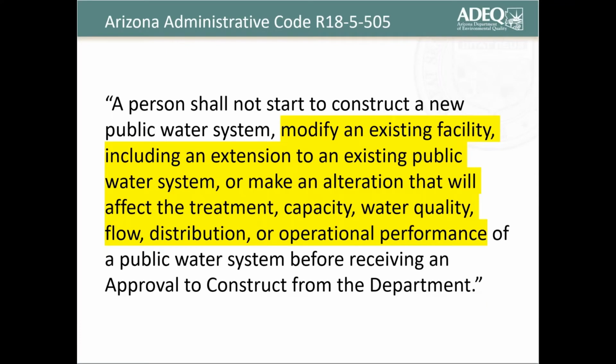Per the Arizona Administrative Code, R18-5-505, construction should not start on any water system before receiving an ATC permit. As seen in the highlighted portion, any change, modification, or addition will need to go through review and proper testing before any water component can be operated. Before construction begins, ADEQ will need to ensure local guidelines are incorporated into the design of these new facilities.